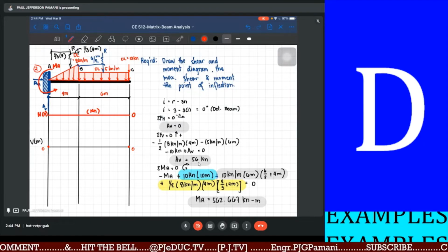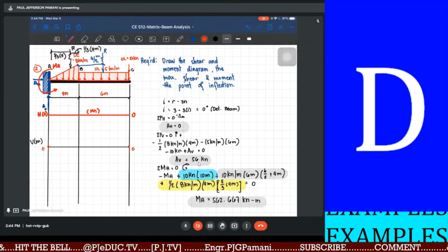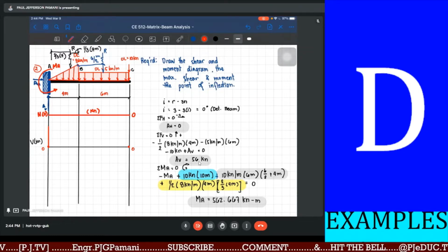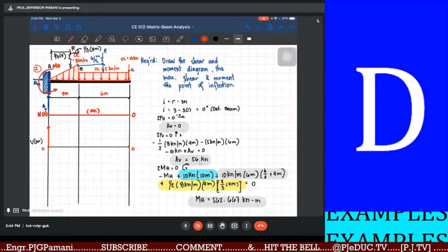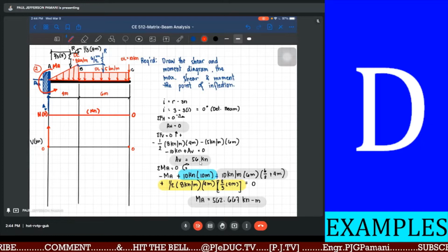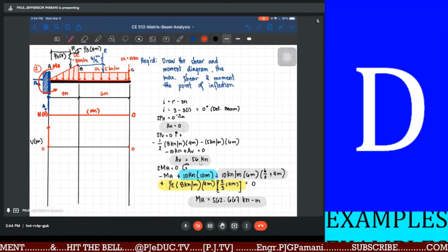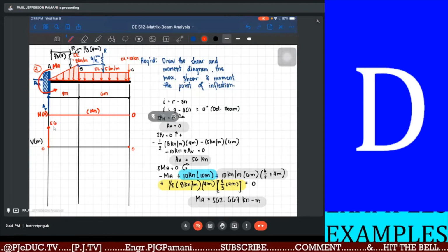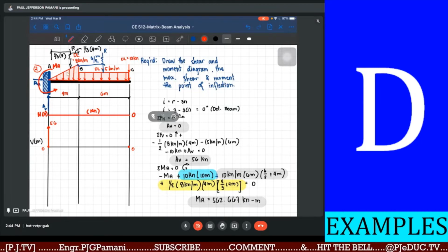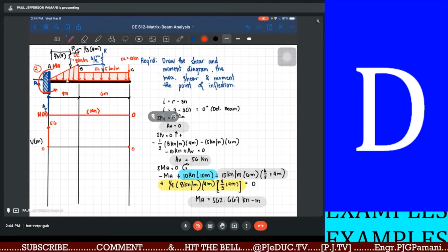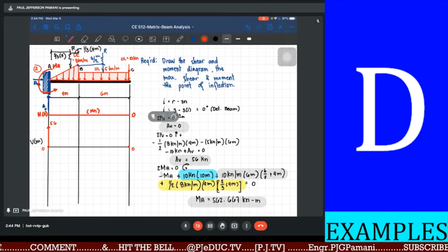So, i-plot natin si 56 kilonewton. Upward. So, upward, 56. Exaggerated yung figure, so kayo na lang po mag-scale later on sa sarili ninyong drawing. So, we have positive 56 kilonewton. So, if that is positive 56 kilonewton, then the remaining applied loads are all downward, directed downward. So, isusubtract lang natin lahat yan.